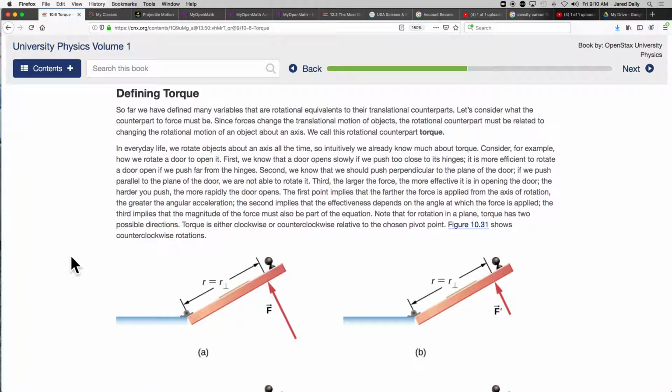In some situations, there is no obvious rotation, so where you pick your point of origin, your 0 point, doesn't really matter. But let's take a look at a door here. You have a door, and it has a hinge, and that is the rotation point. There are plenty of forces that happen at a hinge, and they are not all that simple to define. So we're going to go ahead and pick the hinge as our 0 point, and that is the point where we're going to measure distances. These distances are going to be from that point to where the force is acting. So in this case, we're pushing on the door here near the handle, and the distance from the hinge to where we're pushing is the r vector. It just so happens that this r vector and our force vector are 90 degrees to each other, which makes our torque calculation easier also.